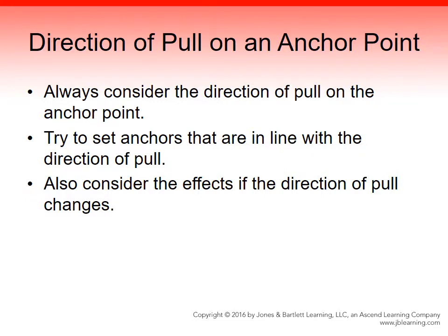Try to set the anchors in line with the direction of pull. Also consider the effects if the direction of pull changes. Some anchors are rigged so that they are strong only when pull comes from one direction. If the direction of pull changes, the anchor could weaken and fail.